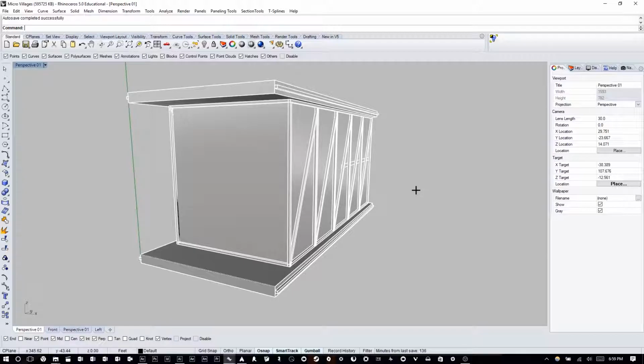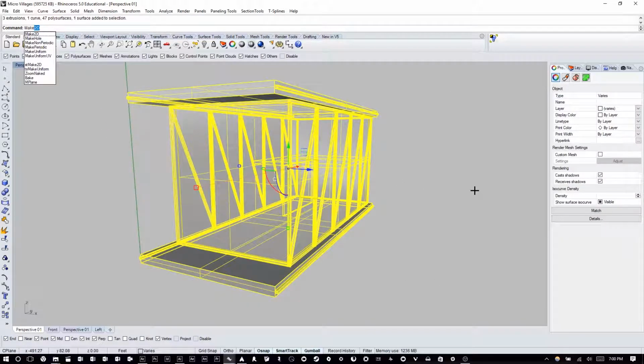When you're exporting from Rhino, there are 2 ways to do so. There is the export command, which exports all the vector lines of everything that you have selected, which could potentially be good or could lead to a very messy drawing. Or you could do what's called a make 2D, which takes the exact vector information that's visible and invisible and separates them for better layer work. So in this case, we're going to use make 2D. It takes all of the 3D vector information and flattens it for our drawing use for 2D.